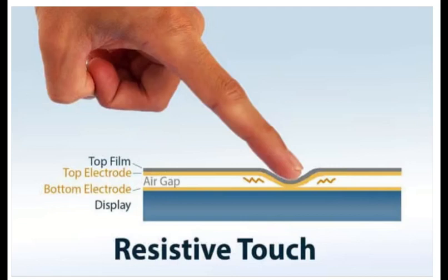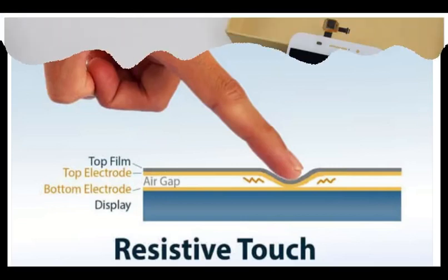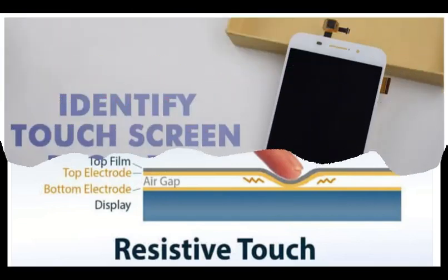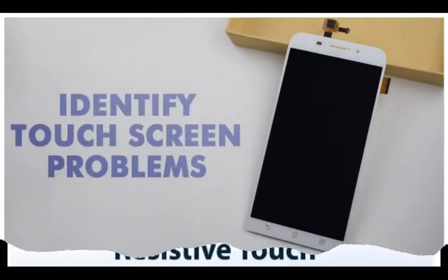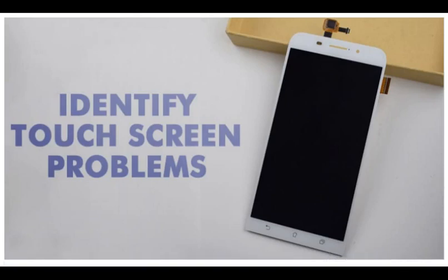Sensitivity to EMI/RFI. Projected capacitive touch screen. Projected capacitive, PCAP, is similar to surface capacitive, but it offers 2 primary advantages. First, in addition to a bare finger, it can also be activated with surgical gloves or thin cotton gloves. Secondly, PCAP enables multi-touch activation, simultaneous input from 2 or more fingers.